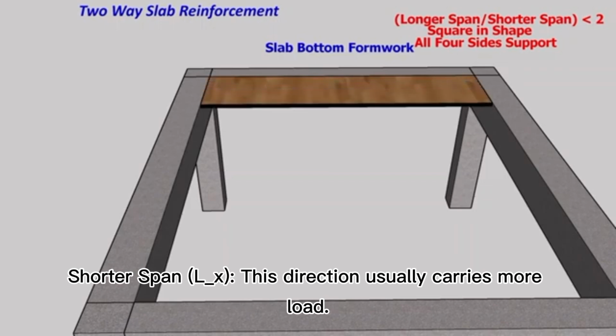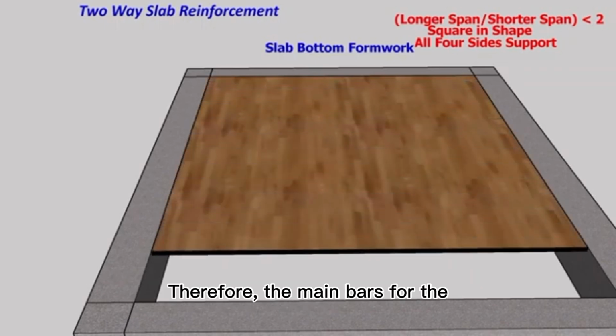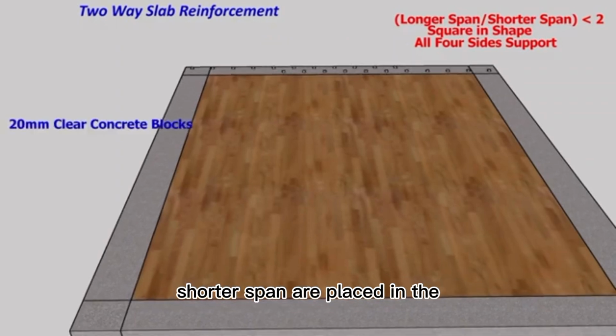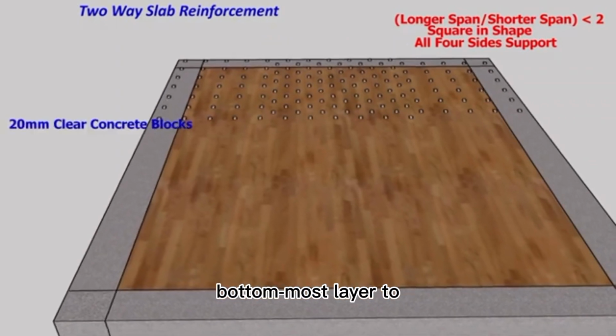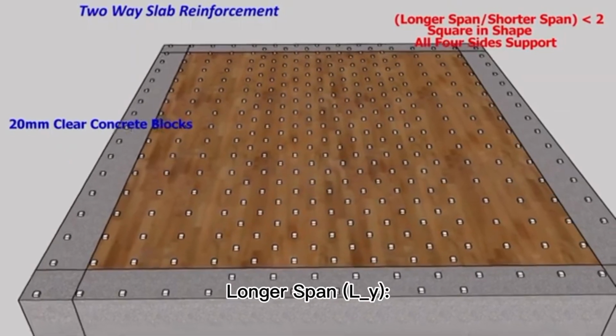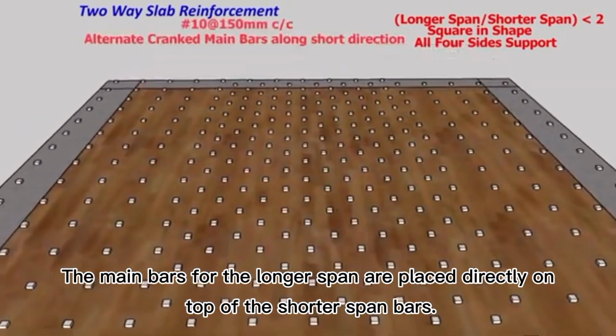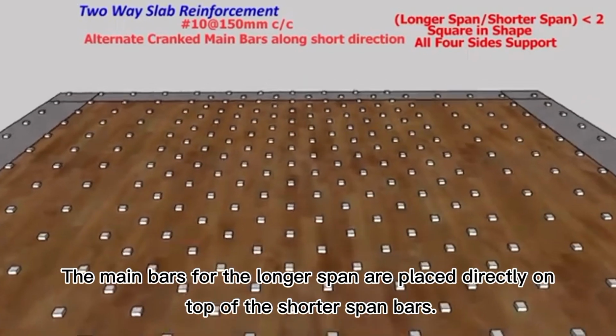Shorter span Lx, this direction usually carries more load. Therefore, the main bars for the shorter span are placed in the bottom-most layer to maximize their effective depth. Longer span Ly, the main bars for the longer span are placed directly on top of the shorter span bars.